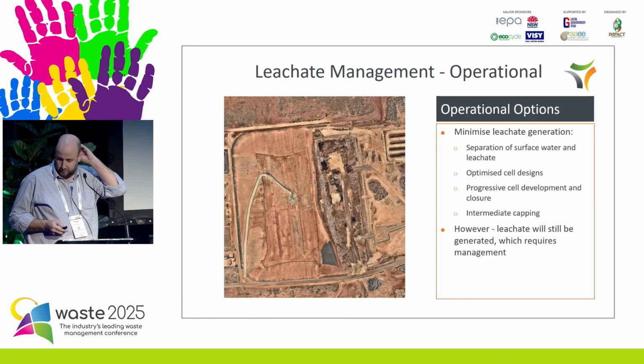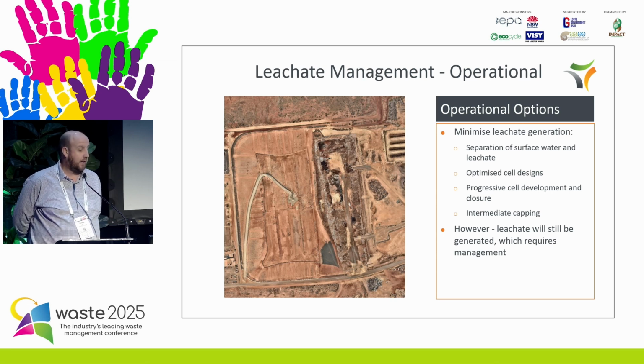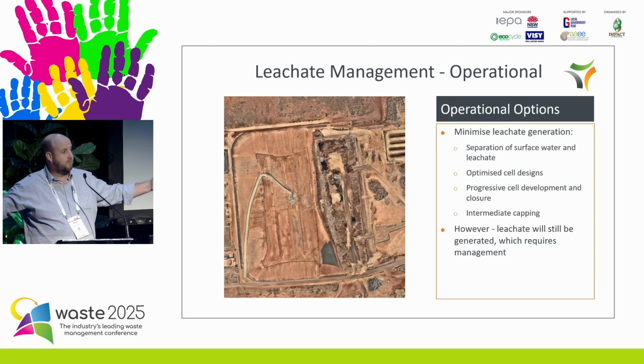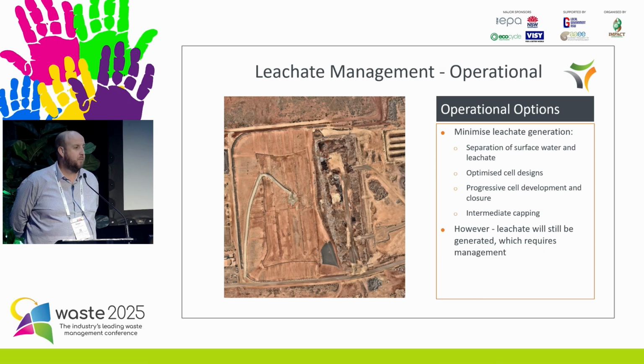First things first, we don't want it, so let's try and minimise generating it. A key part of that, as Kate touched on, was the capping side of things. But even going back to the very early days, it's planning for your stormwater and leachate management requirements from day one of your facility, and optimising landfill cell designs. It's great when you go to a client and say, look at this cell I built, it's 10 years of void space. Well, it's 10 years of leachate generation. So be very smart about how you're designing your cells.